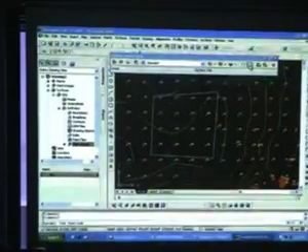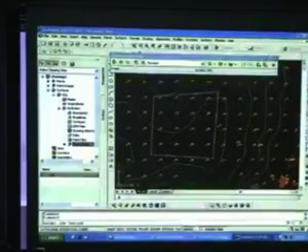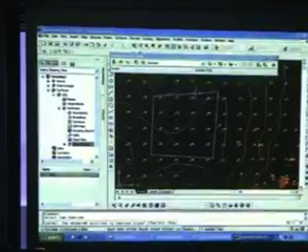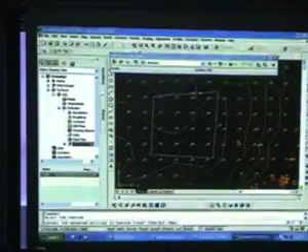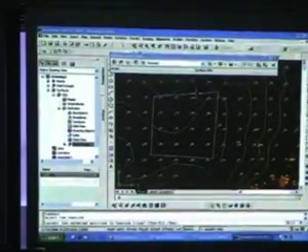Then it'll ask you to select the feature. So just select the white line. Then it will ask you to convert the selected entities to feature lines. This is because for grading, you need to use feature lines instead of normal polylines. What it does is convert this for you, so you just say yes.